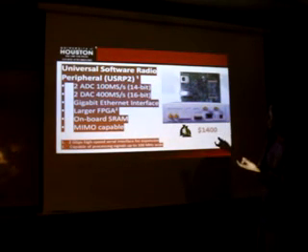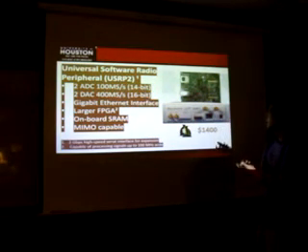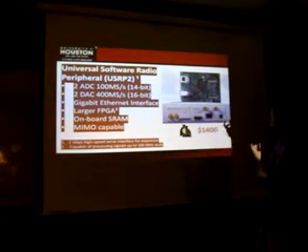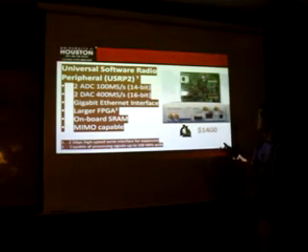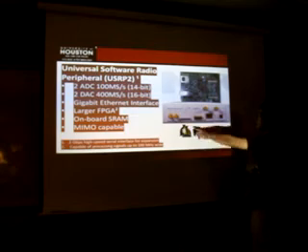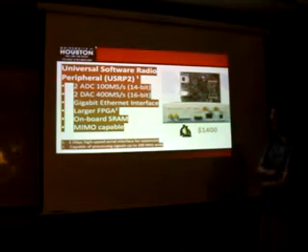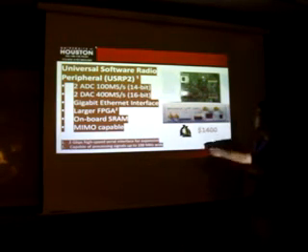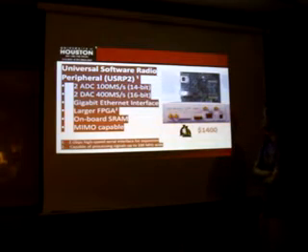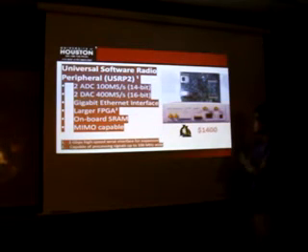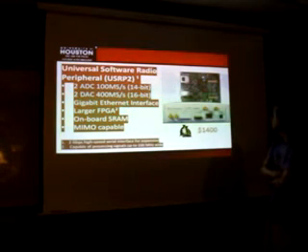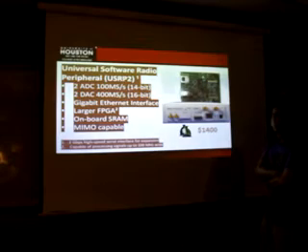The USRP2 has a larger FPGA, so it's more powerful, and it can process the signals faster. USRP2 has an onboard SD card here, so if you do not insert the SD card, the USRP2 will not work. USRP2 supports MIMO. The price of USRP2 is $1,400, double the price of USRP1.